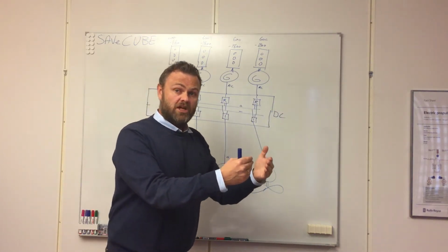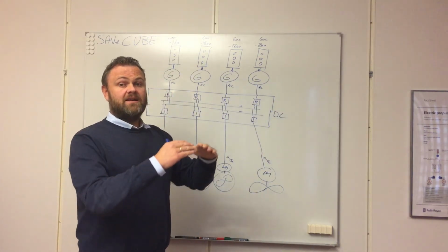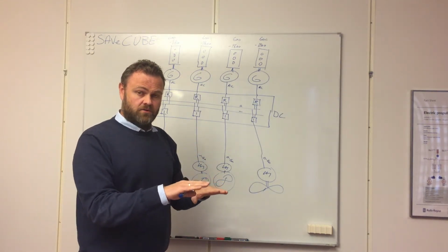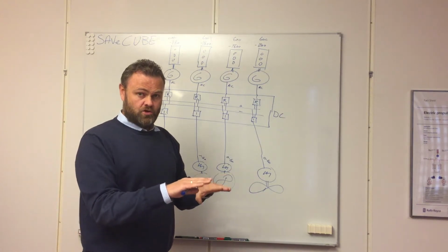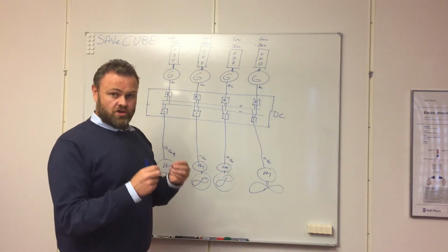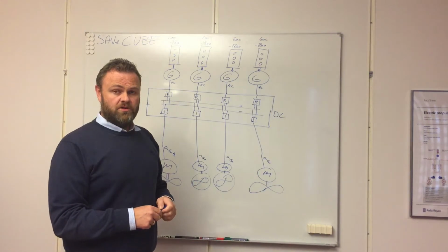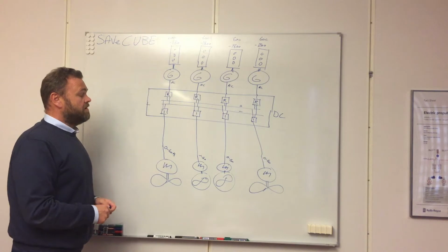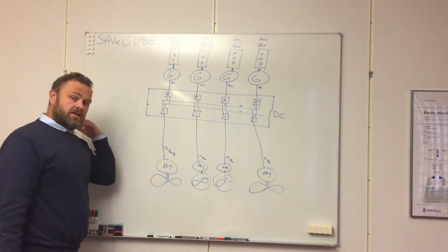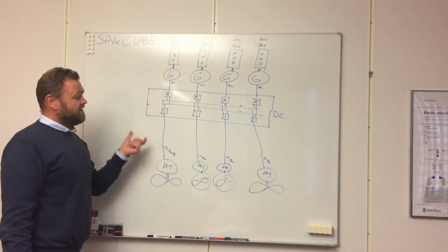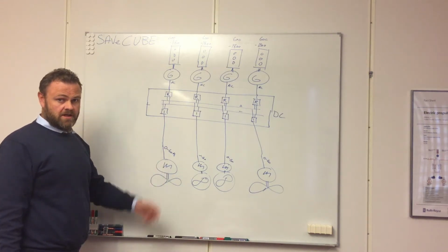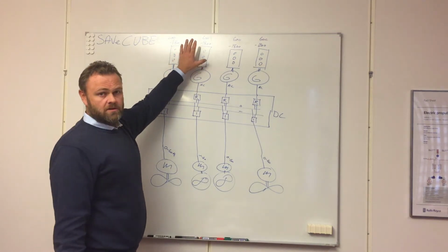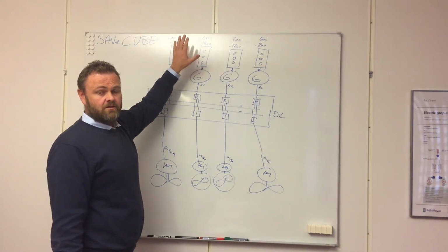So when we need low load, we can as well regulate down the RPM to the most optimum working point for the engine at this particular load. So basically this is the Save Cube. The Save Cube gives you possible variable speed on the main engine.